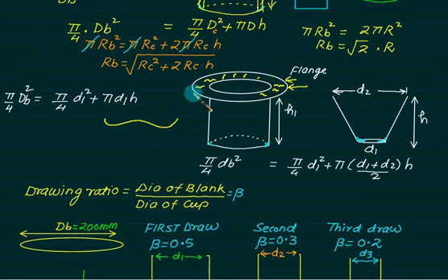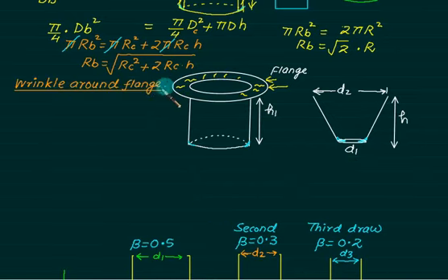You get a wrinkle like this, and the shape will become like this. It's a curved shape. Or we have a crack development. Is the idea clear? So this problem is always there. Normally this wrinkle is because of two criteria. First is decreased blank holder pressure.